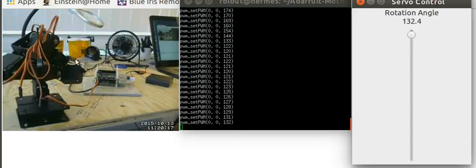Proceed cautiously. I tried to use the example program to test a vertical servo, and in doing so the arm swung itself up and over its head and just barely missed the Raspberry Pi. So again, use a little caution and common sense, and by all means bolt this thing down, because the torque will try to twist the base in the opposite direction of arm travel. Hope this routine is helpful.